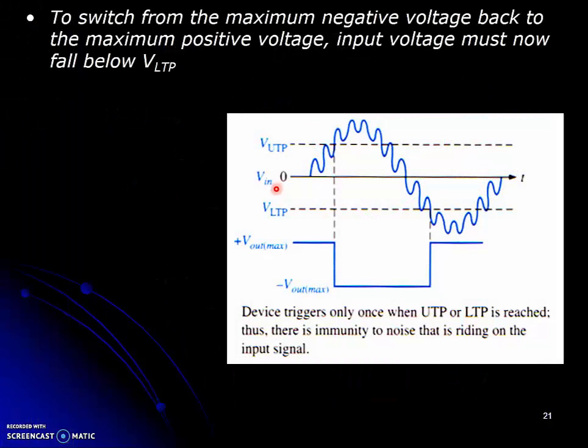We have just discussed that the Vin is equal to the V negative, while the V positive is equal to the triggering point. During this time duration, the V positive is higher than the V negative, so the output stays high. That will change when the input signal goes higher than the upper triggering point. Then the V negative will be higher than the V positive, so the output is forced to switch from high to low. And this switch in the output will change the upper triggering point to the lower triggering point.